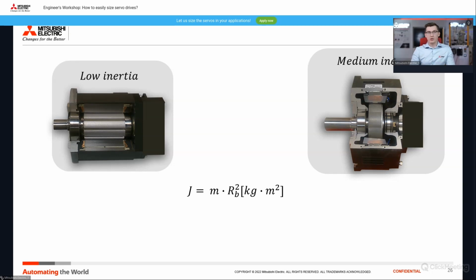There is one other thing: the radius is bigger, because the equation for torque is just the force multiplied by the radius at which you apply this force. In the motors, the force will come from the electromagnetic force, and this will be applied to the magnets.